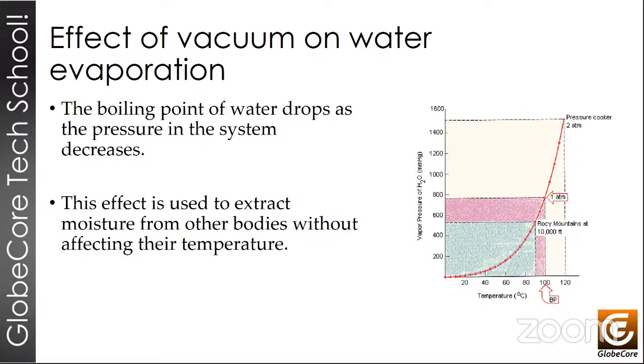So what we do, we subject the oil to reduced pressure, or vacuum, directly affecting the water inside that oil, because now water can be extracted quite easily without damaging the oil by high temperature. The lower the pressure that we can achieve, the higher the vacuum, the lower the temperature that we need to apply to separate water from oil. And as we can see, this is a purely physical process.